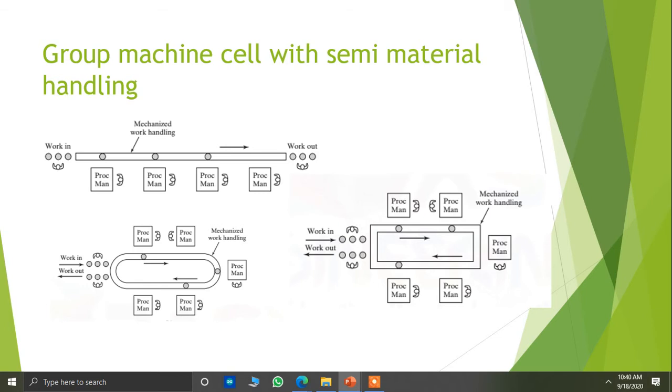Okay, so the structure might vary, but it is more or less the same. The drawback of the last two is that if finished goods are being transferred, that's a waste of time and energy. So there should be some arrangement such that there will be a bypass movement of the conveyor belt or material handling system, where on one pass you have semi-finished or finished goods, and the second one will have completely finished goods, right? In that way that problem can be avoided.